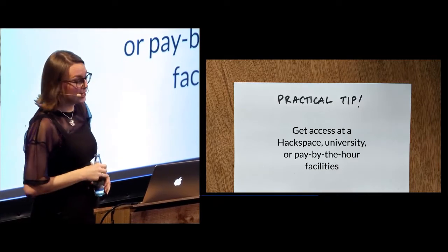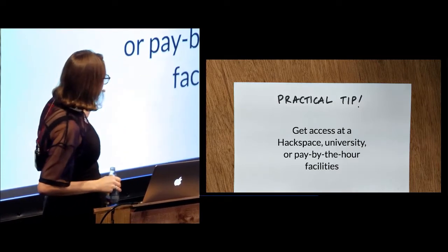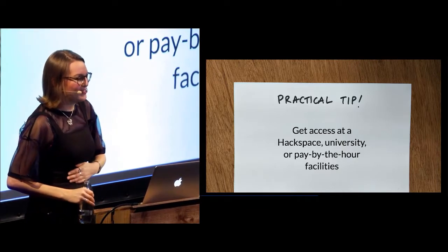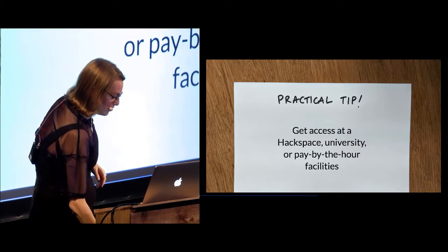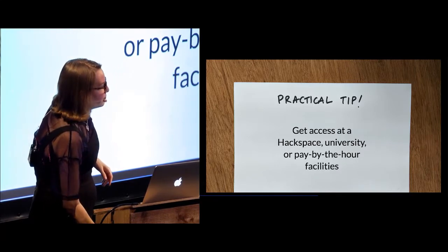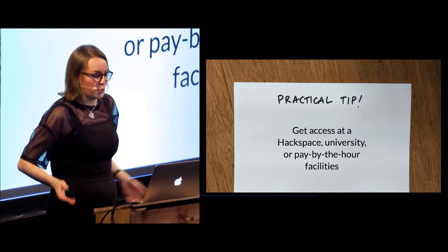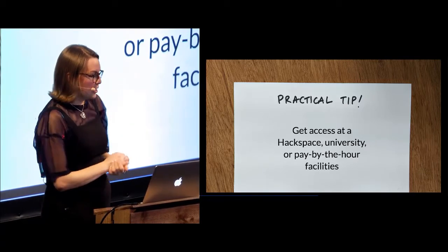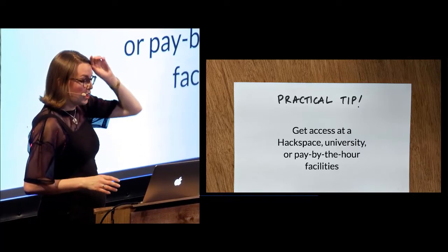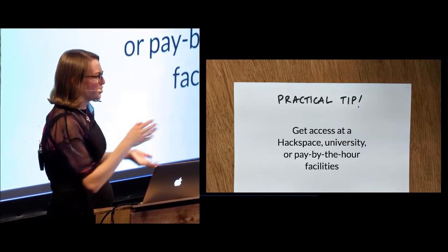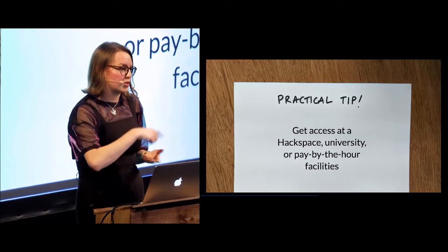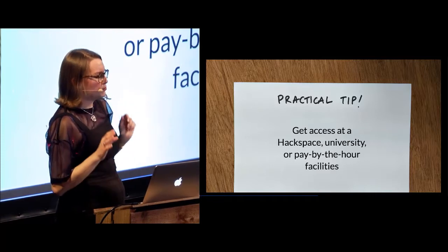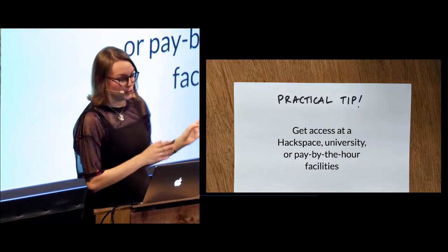Practical tip for laser cutting: get access at a hackspace, university, or pay-by-the-hour facility. Laser cutters are extraordinarily expensive. The one I had at university cost £60,000. You can get cheap ones for as low as like 200 quid, but I really wouldn't recommend that because they're lasers, they're very dangerous. They also need proper ventilation. But also, if you get a cheaper one, it's going to be less powerful, so everything you do will take a longer amount of time, and there are quite a few trade-offs there. You're probably better off going to a place that has a good one already.